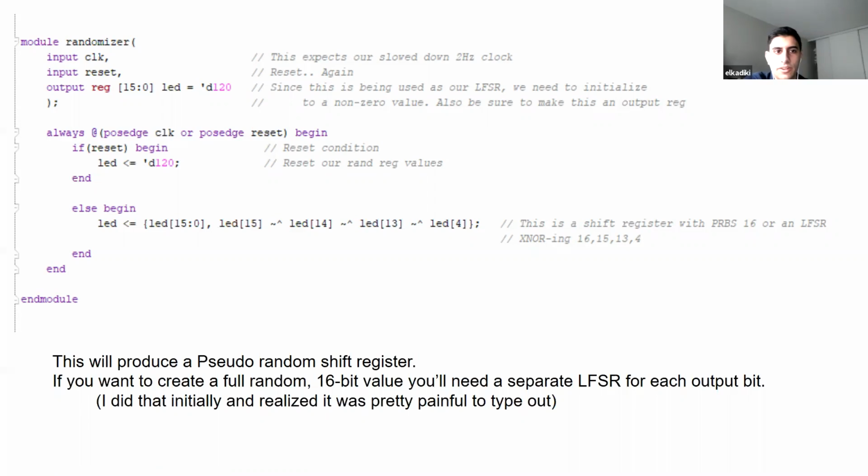Sometimes Vivado is smart and realizes that you're trying to go for a decimal value, but it'll still complain about it. If you have 120, that can't be binary, right? But if you have the number 11, that's either binary, hex, or decimal. And 11 is not equal to 1, 1, which is 3.